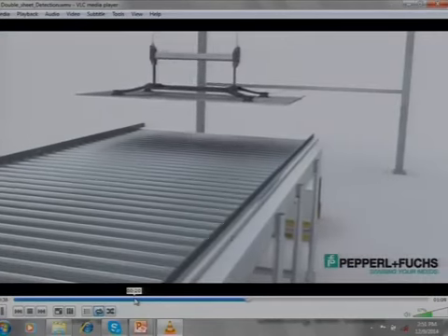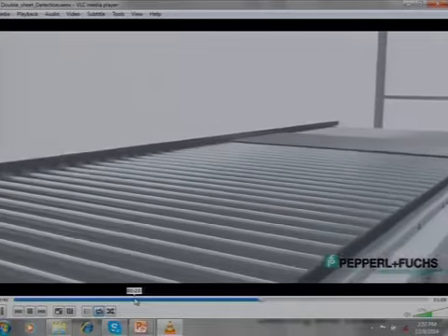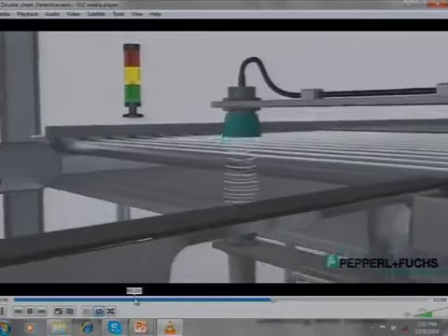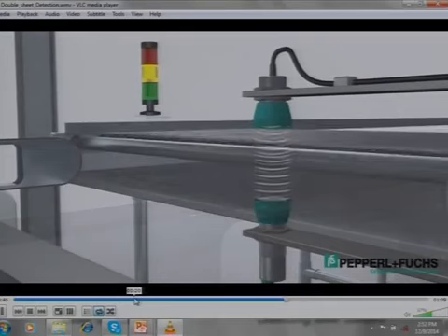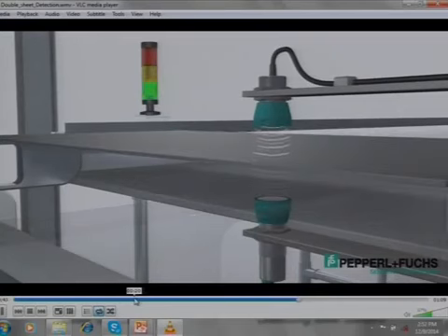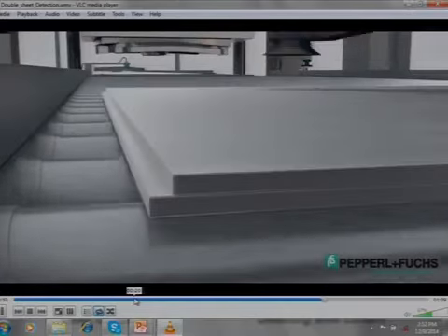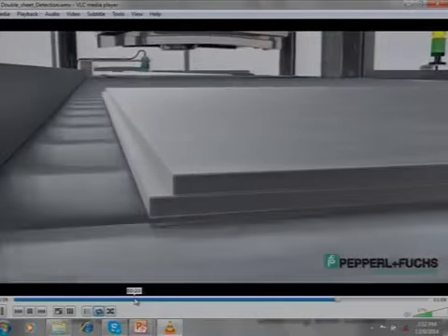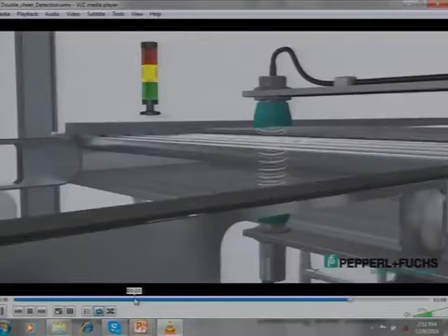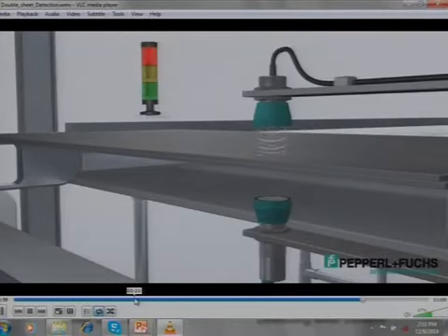The sound waves get reflected from one surface, that is one sheet, then there is an air gap, and then the second sheet. The sound waves get reflected from the second sheet as well. The amplitude of sound being received by the receiver is quite less as compared to that received through a single sheet. So based on the amplitudes, we can compare whether there was a single sheet, a double sheet, or no sheet.